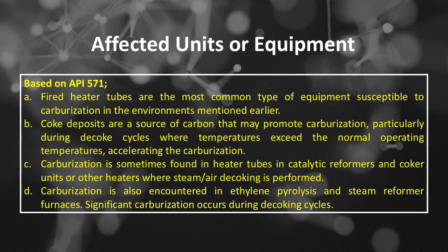Number C. Carburization is sometimes found in heater tubes in catalytic reformers and coker units or other heaters where steam/air decoking is performed. Number D.